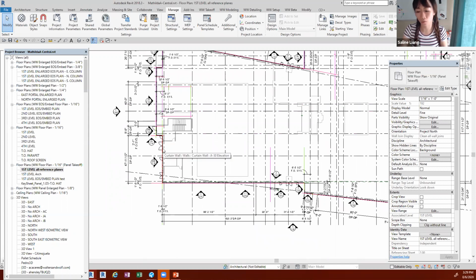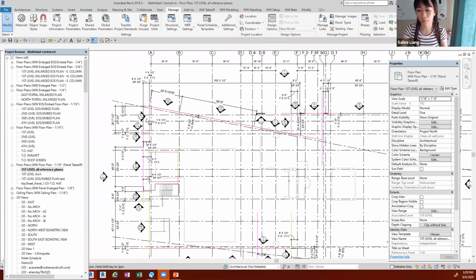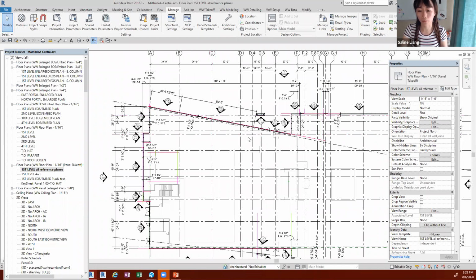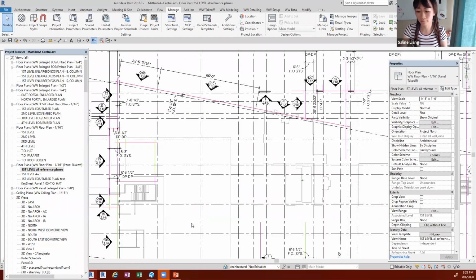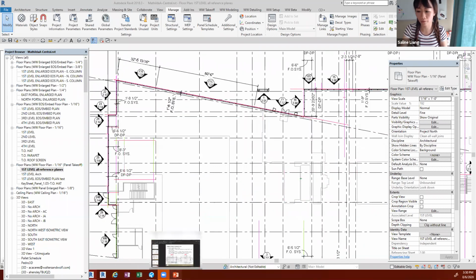The thing is, you always need to think about updating your model, and at the same time update your reference planes for sure. But there's no need to remake these dimensions, right? You can easily just edit that, or use your reference planes to lay out your model, to make sure this is the right dimension point, and there's no doubt when you look at the reference plane.